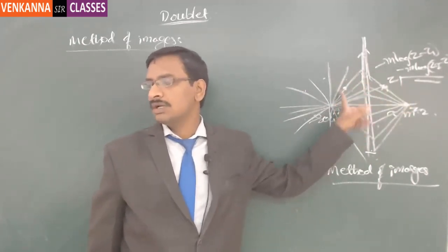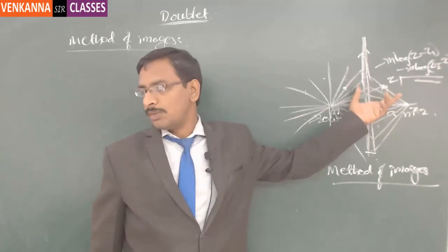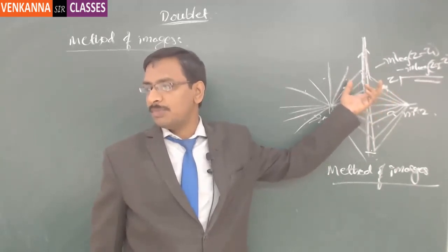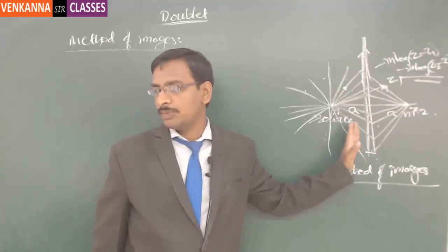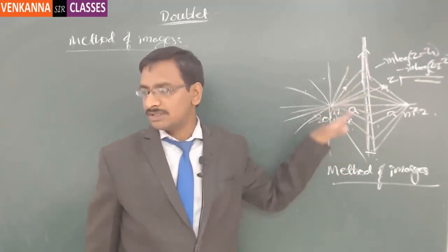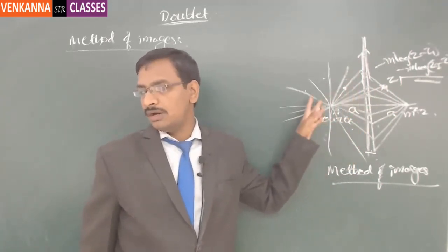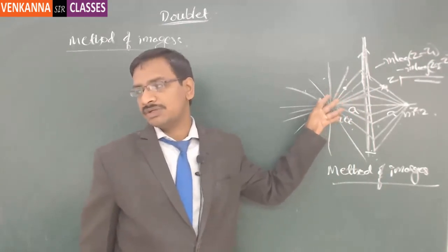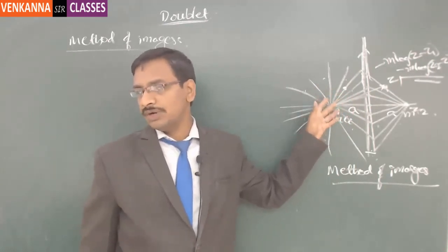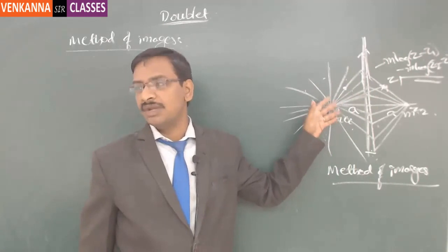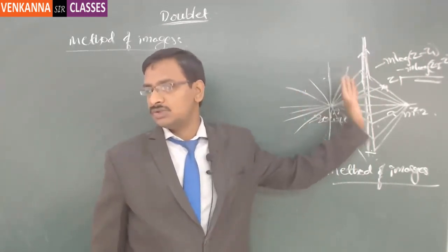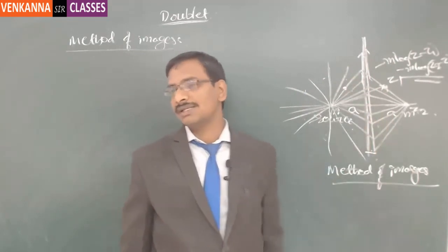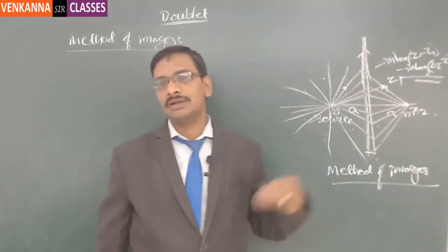All these locations, the streamlines or the complex potential or the scalar potential, will be perfect without any mistakes, even though there is a wall. Because without the presence of any surface, we learned the value of the complex potential at any point of time, what the fluid direction is, that is the stream function, and what the equipotential lines are. All those things we found with an assumption that there is no hurdle in between. But in certain cases you may get hurdles, as in the case of dams.